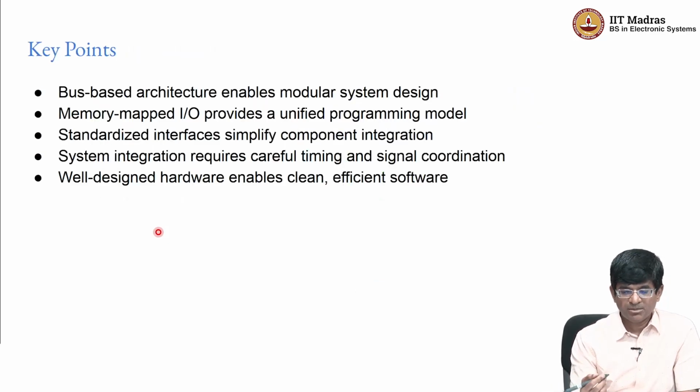So to summarize, the bus-based architecture is what enables modular system design, or rather is one of the approaches that enables modular system design. Memory mapped I/O provides us with a nice unified programming model, right, which is nicely exploited by the bus-based architecture. Having standardized interfaces or a standardized architecture for the bus simplifies component integration. There are multiple buses in existence. Intel uses their own bus architectures for the peripherals that are tightly integrated with their CPUs. There is something called the Wishbone bus architecture that was defined as an open standard.